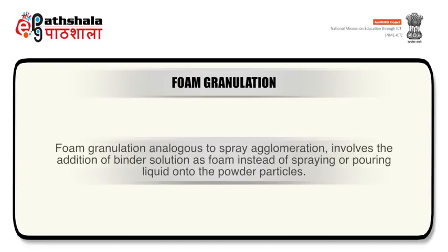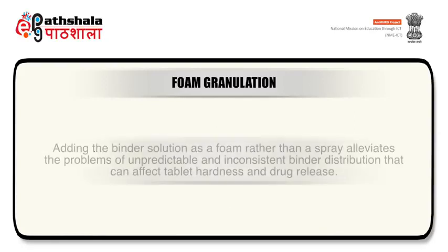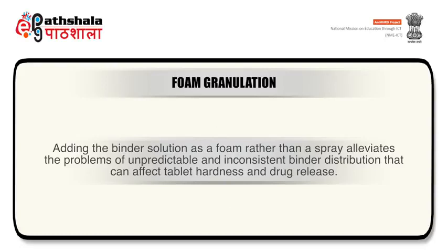Foam granulation is analogous to spray agglomeration, with addition of binder solution as foam instead of spraying or pouring liquid onto the powder particles. Adding the binder solution as a foam rather than a spray alleviates the problem of unpredictable and inconsistent binder distribution that can affect tablet hardness and drug release.